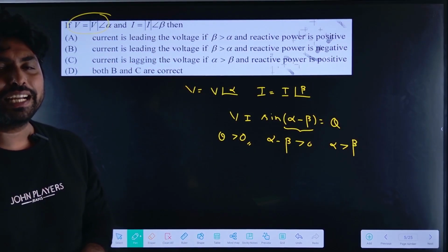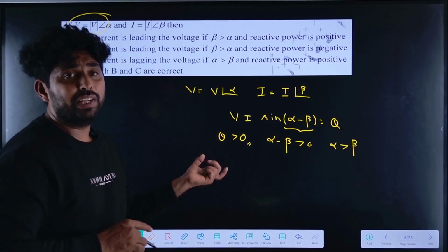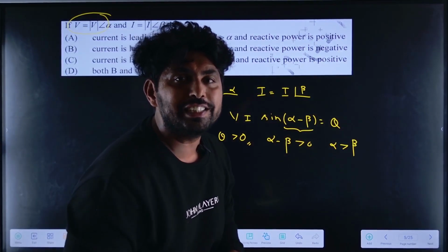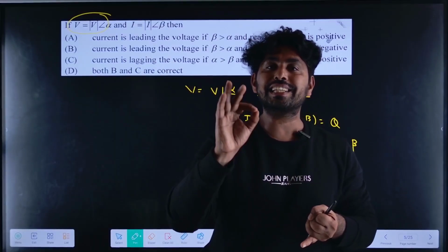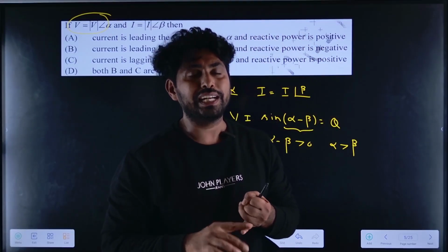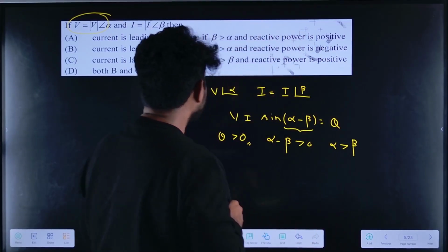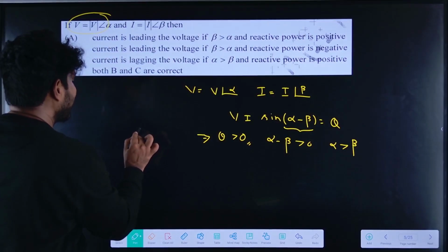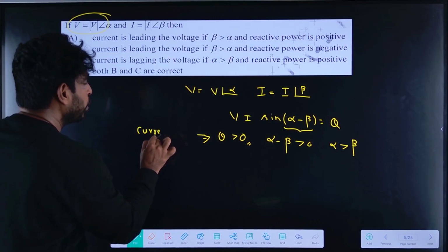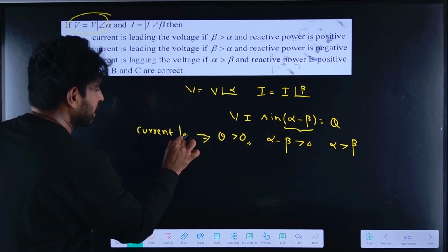When will the reactive power be positive? When it is inductive reactive power, that is lagging reactive power. In an inductive load, current lags the voltage.